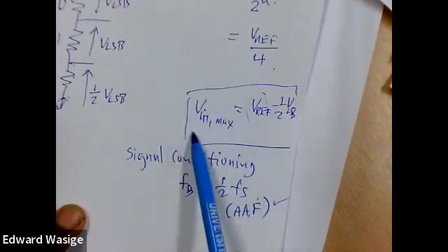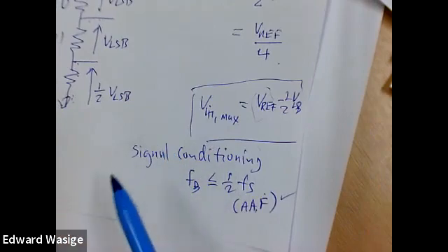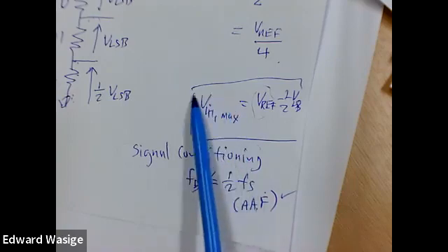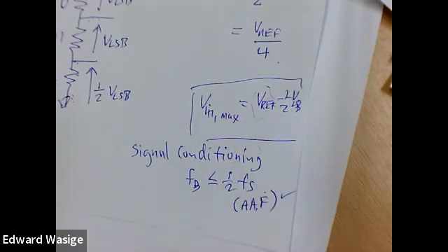Similarly, the input amplitude voltage, we cannot just have any random voltages coming into our ADC. So we do also signal conditioning for that. We know what kind of amplitude voltage is coming, and the maximum input voltage will be slightly less than Vref. Of course, if it was bigger, then we'd have to choose our reference voltage differently.